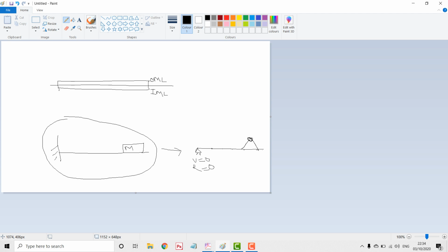The weight will be mass times the gravity, 9.81. Suppose your mass is 10 kilograms, then the equivalent force will be 10 times 9.81, which is 98.1 newtons. The software, while running the analysis, while solving the problem, will apply 98.1 newtons at those nodes.